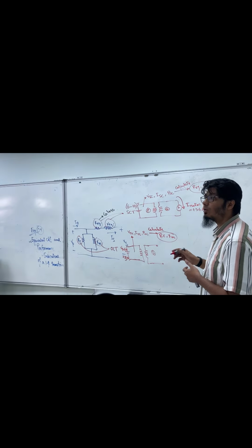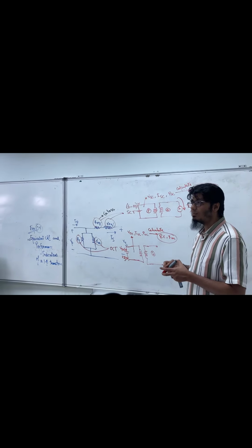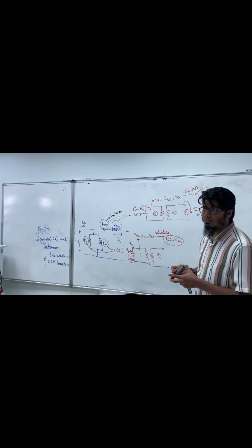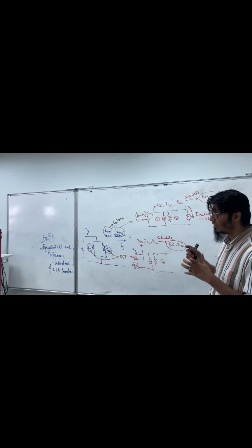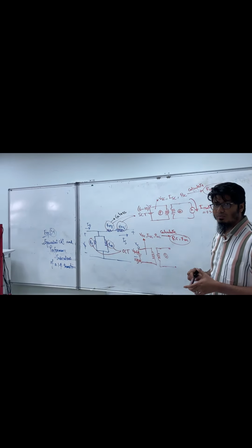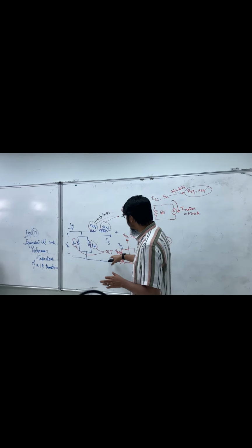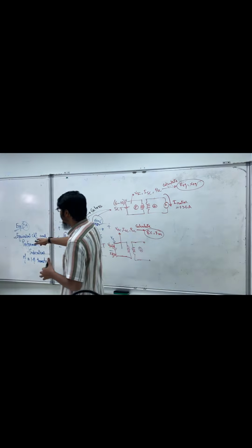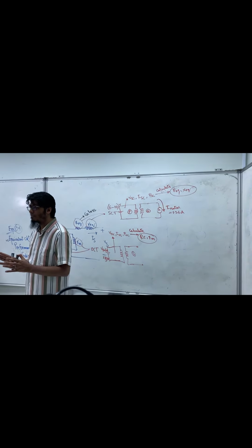This can be a question: why do we use an extra ammeter at the time of short circuit test? Because the current is high. You need to see carefully whether it is crossing the rated value or not. Clear, guys? So this is the open circuit test and short circuit test and the equivalent circuit parameter calculation. Do you have any question from the first part?